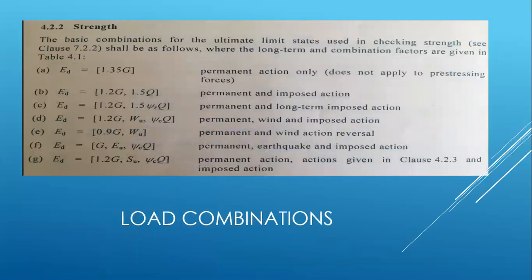Australian Standard 1170.0 provides load combinations for checking the strength of the structure. These combinations add dead, live, and wind loads together. The engineer can then determine the load with the highest value, called the critical load, and design to cater for this load. Load combinations build a factor of safety into the structural design and are designed to cater for infrequent additional loads, such as unusually strong winds or increased live load, such as people walking on the roof of a structure.